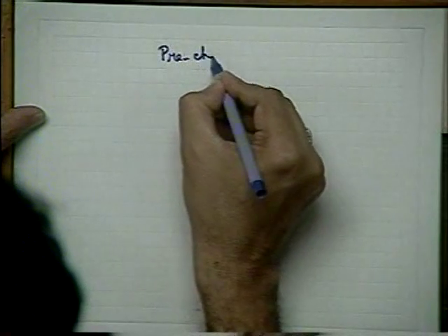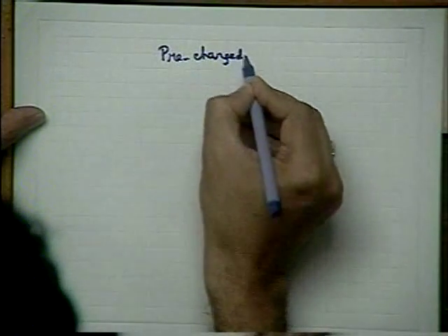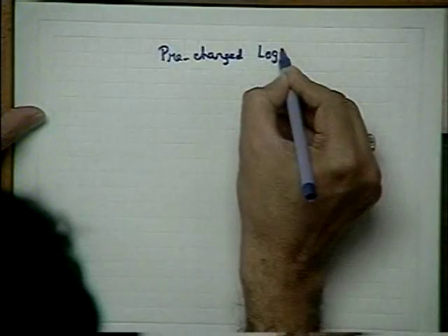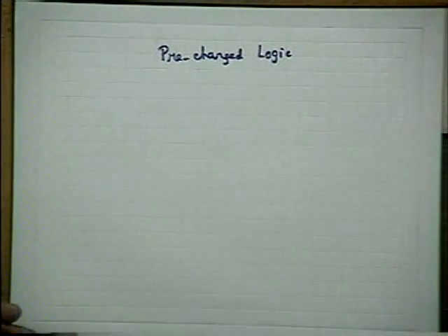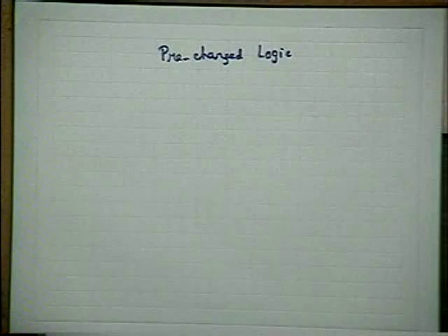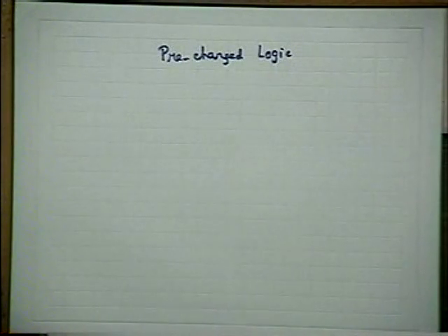The advantage is that you can have synchronous operation instead of asynchronous. For synchronous operation, there are a lot of advantages from the timing point of view, and for any synchronous operation, we prefer to use Precharged logic in place of standard static logic.